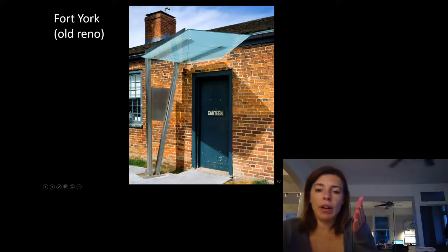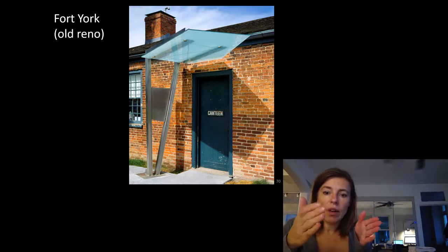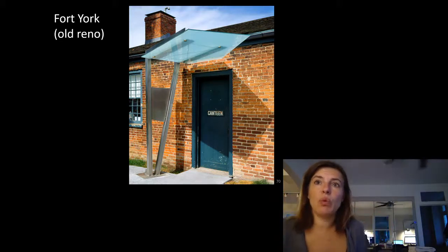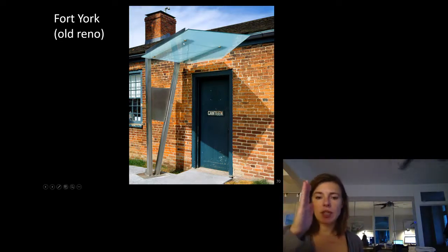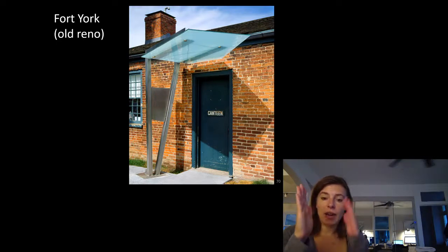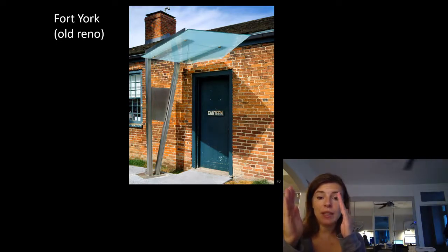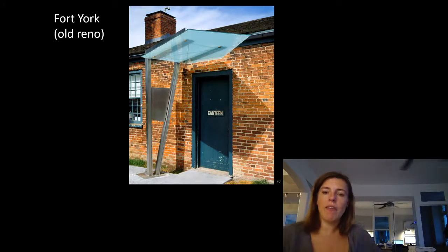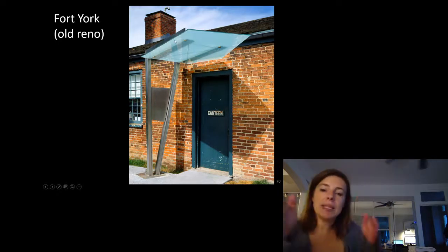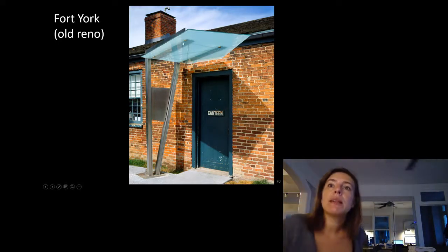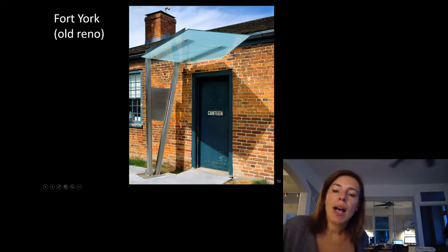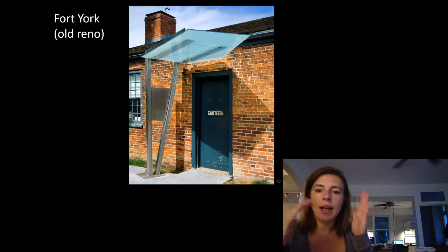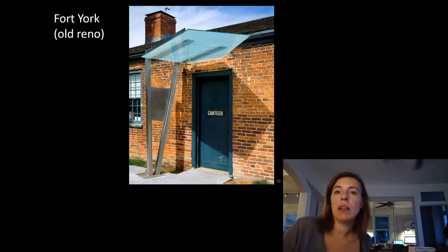These didn't work for wind drag on it, or it didn't work enough to satisfy everyone on its movement. Because glass, as much as it can be loose in deflection in that direction, it's not as great in plane. It's so stiff that if the things it's connected to aren't that stiff but strong, you can end up failing the glass. So this needed to be stiffened in the plane of the glass. You can see these rods or cables would have been tightened to resist that tendency to rack under wind loads.